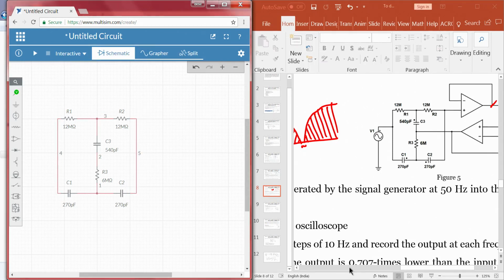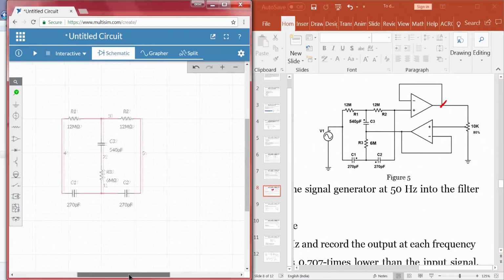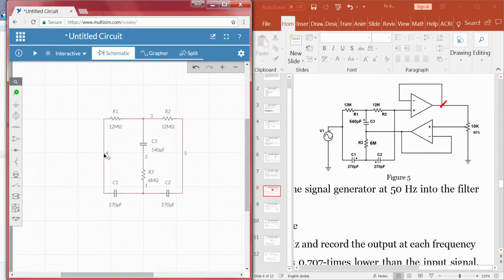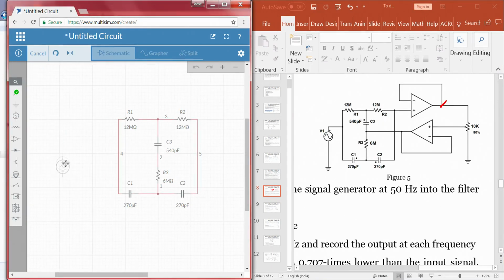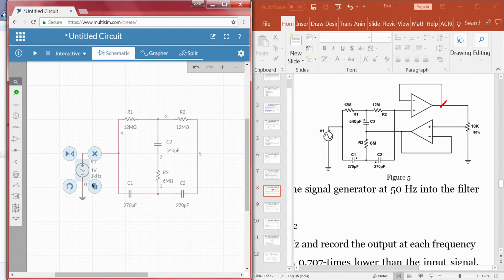Right. So, which looks similar to that of our circuit if you observe here. Now, the input should be connected at this point. So, what I will do is take an AC voltage, connect it here, and the other terminal should be connected to the ground. We are thinking of taking a voltage source with an amplitude of 1 volt peak value. So, peak to peak we can select it as 2 volts too, right. So, it is relatively easy to understand our output voltage.